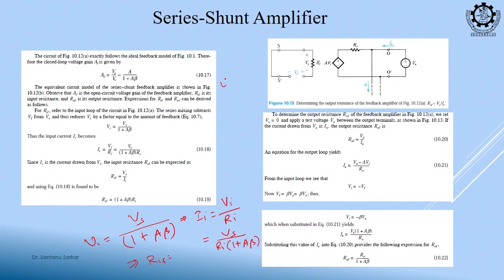Okay. So, using negative feedback my input impedance is increased, and is it helping or is it wanted? What is wanted, right? In a voltage amplifier, input impedance should be as high as possible. So, negative feedback is helping in increasing the input impedance.